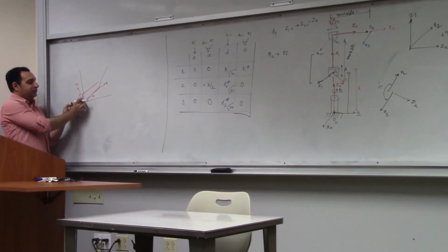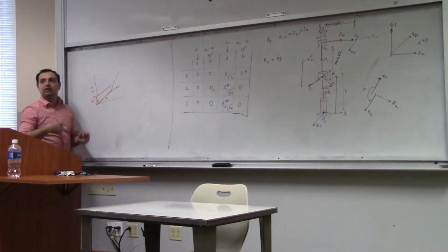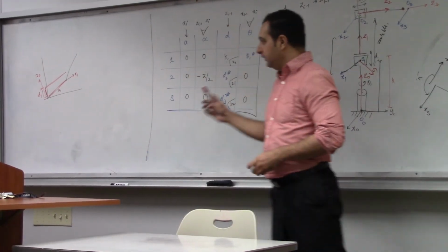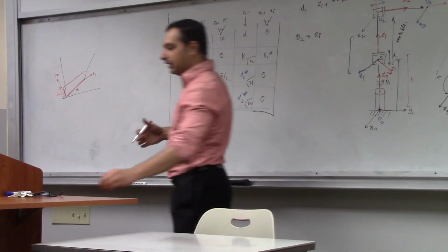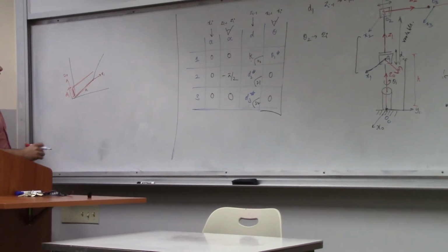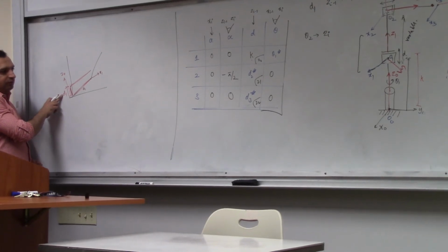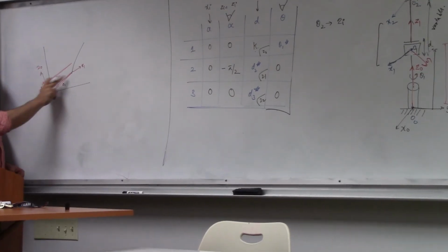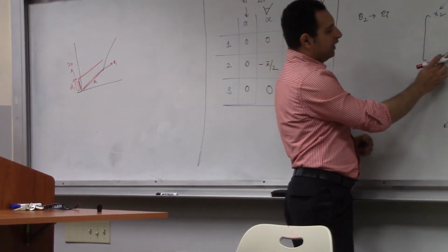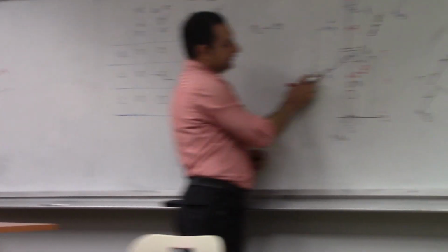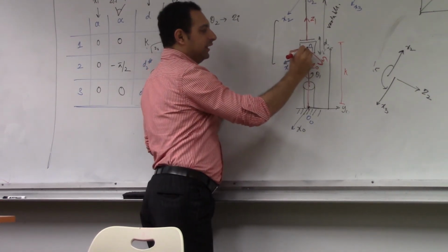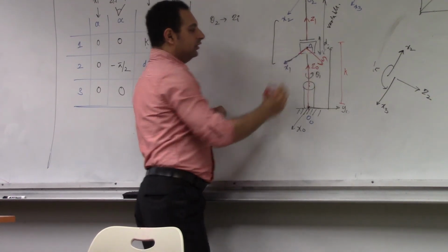In this case, what you do is you'll actually have to move the origin. We'll discuss that. That is a little specialized problem, but we'll do that once we get to understanding how to do this. Okay, so I'll give you one more question. Actually, SCARA will have one link which also has A and D at the same time. So if I want to have x at the value of A1 at the same time, then there has to be a distance like this. So the link will be like this.